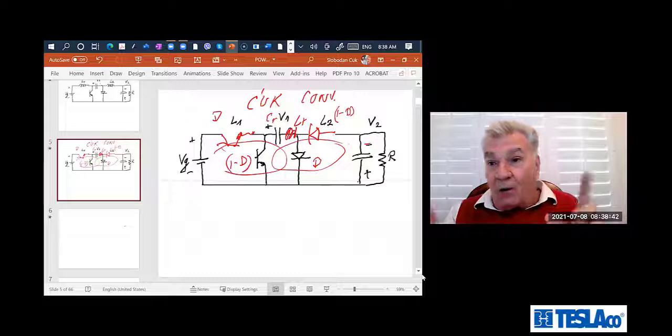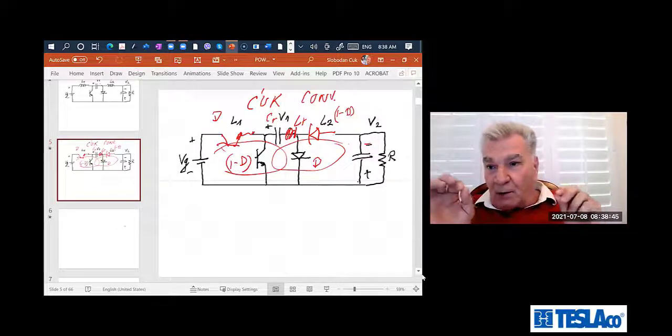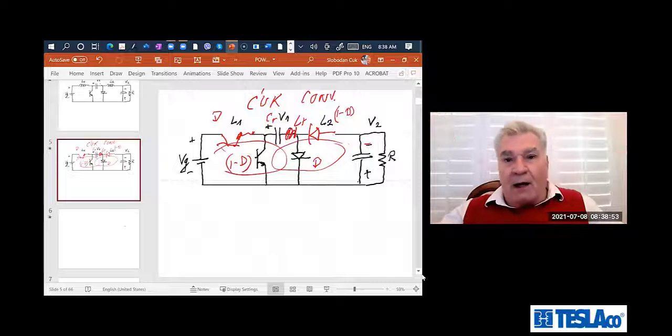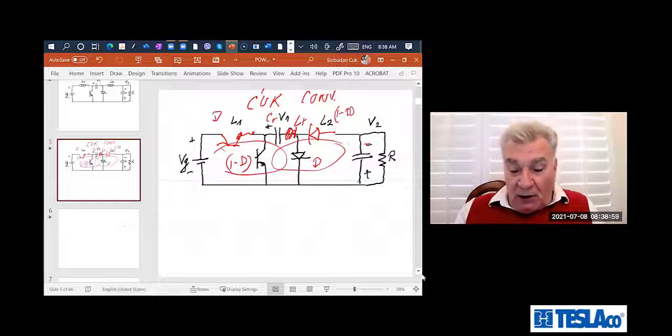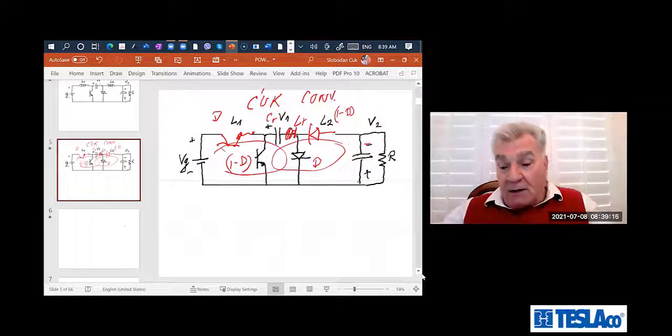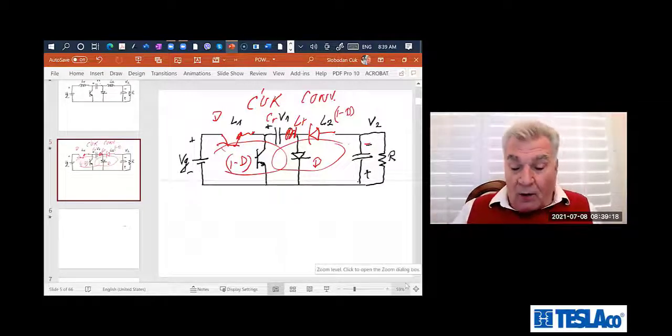And then I'll have this other resonance. So now you see what I'm trying to point out. Remember, I showed you this presentation from Google, when they had 10 switches, then 12 capacitors, 5 or 6 inductors, and a bunch of switches. Here we have just 4 switches, and they are in synchronism. These 2 switches operate together like a voltage-bidirectional switch, and this switch is like a split voltage-bidirectional switch, because you have a transistor and diode, which is really a voltage-bidirectional switch, which maintains resonance only in on time or off time.